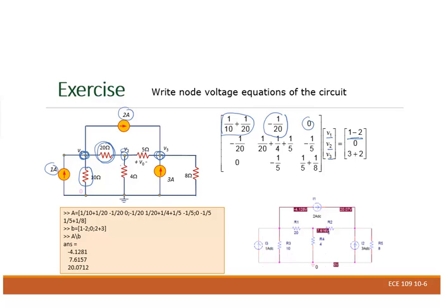When we write the second equation, between 2 and 1, we have 20 ohms, negative 1 over 20. That's why you have it right there. 1 over 20, 1 over 4, and 1 over 5, we have it here. That's going to be right here. Between 2 and 3, we have 5 ohms, negative 1 over 5 will be right there. Okay, node equation number 2, there is no current directly connected right there, that's why it's going to be equal to 0.